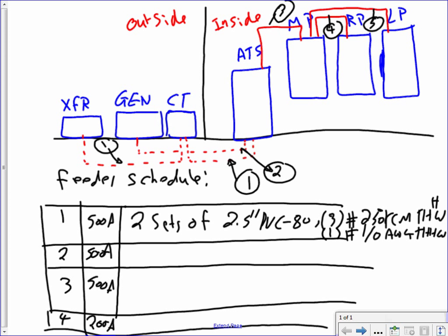The second way, you guys can easily do that, right? In CAD, go draft it, import it into Revit, put it in the right location, check, done. The second way that we're going to do is, I call it the best way. The best way is to design everything in Revit, put the families, and then connect them with pipe. Bring an actual pipe and connect them in 3D. That's the best way. That's the rich man's way. Now we're going to find the happy medium between these 2 ways. The average man's way is what we're going to be doing. We're going to do a hybrid of Revit and CAD.